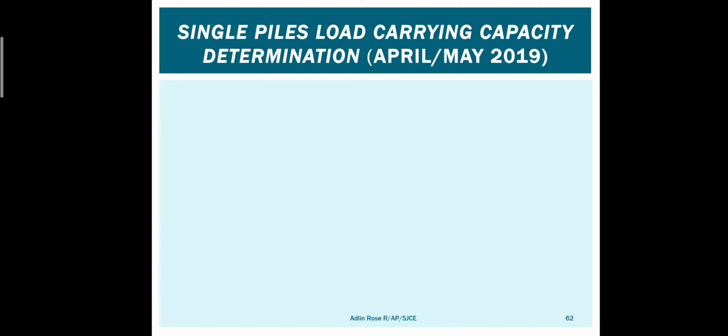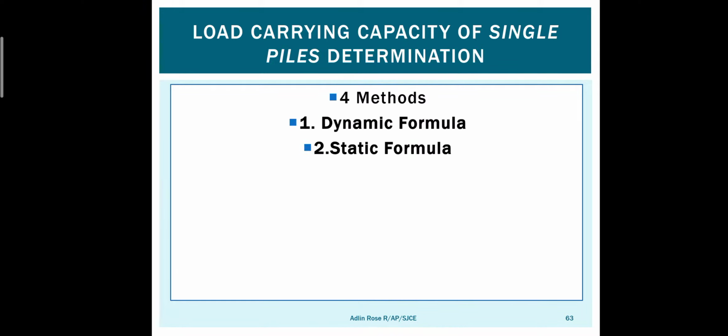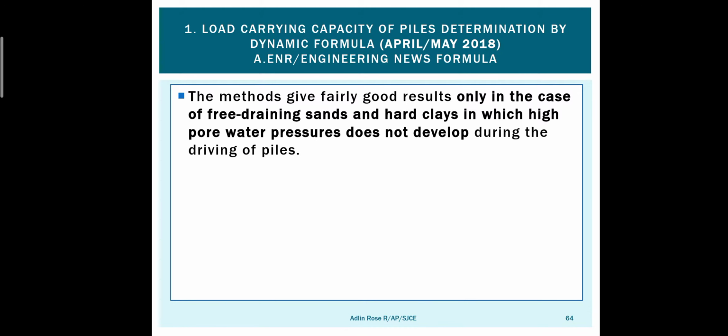Okay, single pile load carrying capacity. First we will start. As I said, for a single pile we have 4 methods. One is dynamic formula, second is static formula, third is pile load test, and fourth is penetration test. First we will see the dynamic formula.